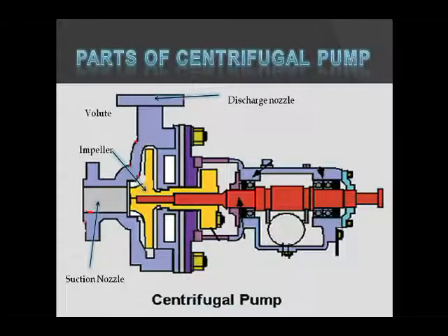After discussing the impeller, we are going to explain the volute. It is a casing that receives the fluid being pumped by the impeller. The volute converts kinetic energy into pressure by reducing speed while increasing pressure at the same time. After this, the seal of the pump is shown. Paying proper attention to seals can improve pump performance and life.